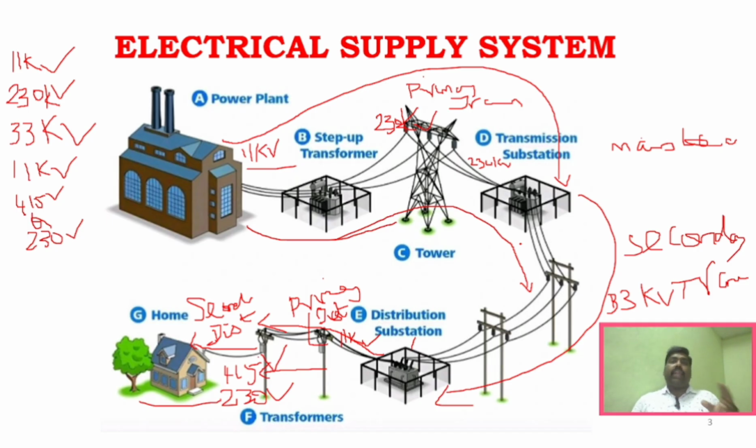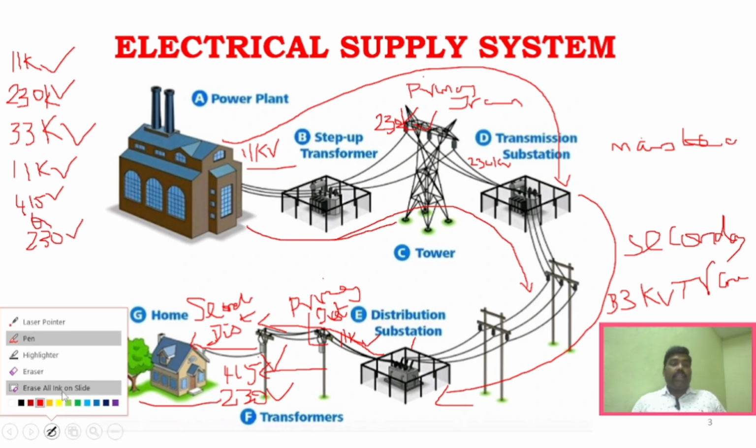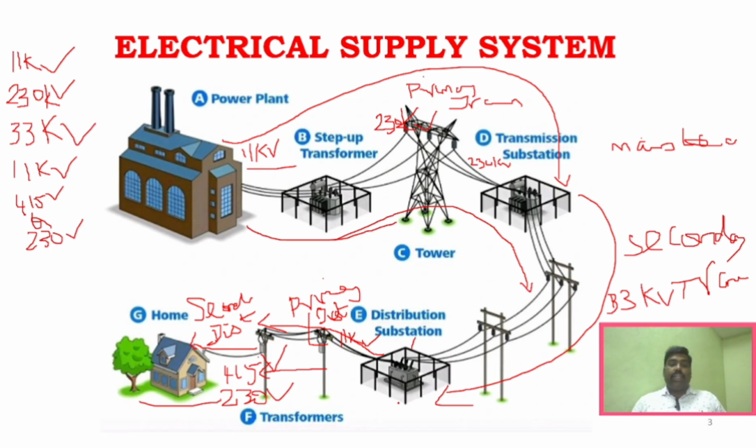And another thing you have to understand here is the different lines. You have to understand what distributors are. So if you see here, from this distribution to this particular point, these are called distributors. These transformers are called distribution transformers, right? And this line from the substation to this distribution transformer, that is called the feeder line, right? And this particular line is called the distributor line.